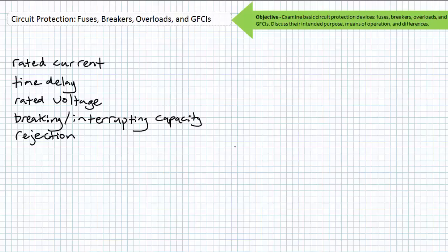The time-delayed action of a slow blow fuse is a heat transfer relationship between current and time. The higher the current, the faster the fuse will blow. The lower the current, the slower the fuse will blow. Ideally, the inrush current for a motor and a properly sized time delay fuse will be quick enough to prevent the time delay fuse from blowing.